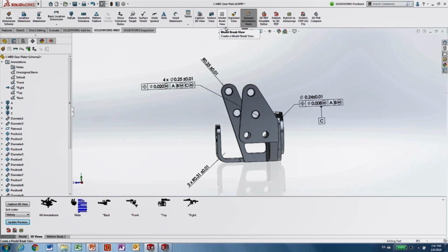So let's say you want to move completely, but you still have that one or two cases where you need to create those 2D drawings. What you can do is create everything in 3D, do the whole thing we just did here, and if you have to create a 2D drawing, you can simply create a 2D drawing like you would, but instead of dragging a view and adding dimensions, you can simply drag your 3D view into the 2D drawing. So if you have to do both for a while as you transition, that can also help you make this process easier.